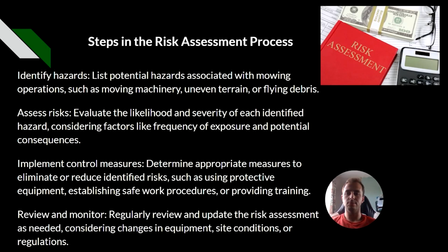Steps in the risk assessment process. First of all, we need to identify the hazards, listing potential hazards associated with mowing operations, such as moving machinery, uneven terrain, or flying debris. Assess the risks, evaluate the likelihood and severity of each identified hazard, as I mentioned before in that table, considering factors such as frequency, exposure, and the potential consequences of those hazards.